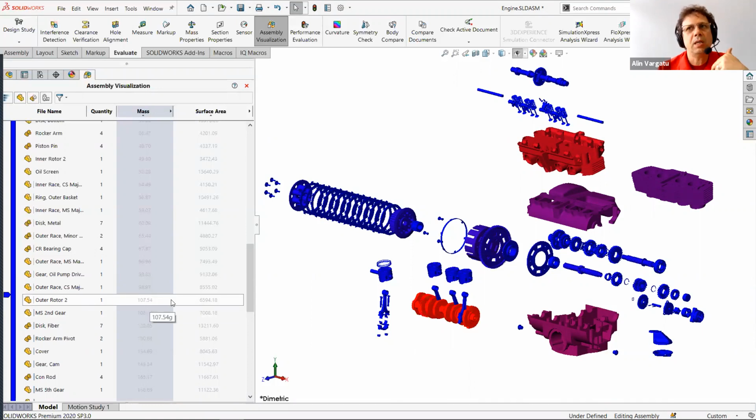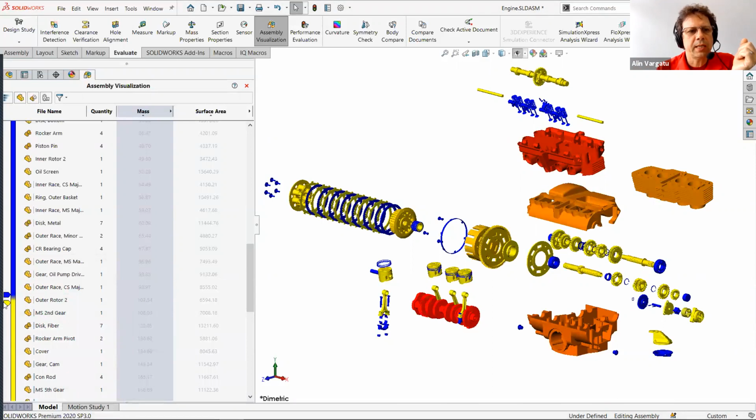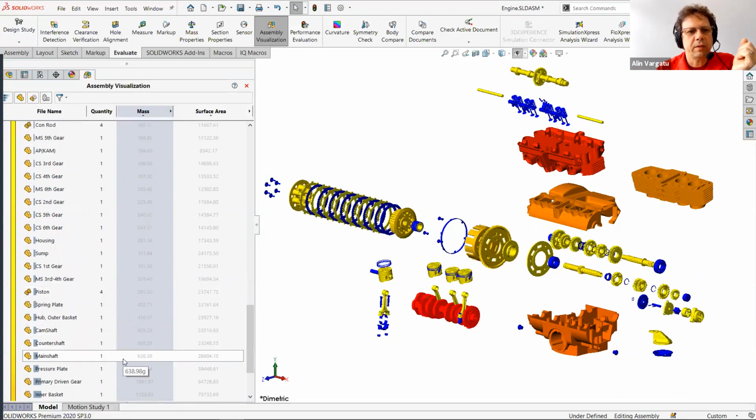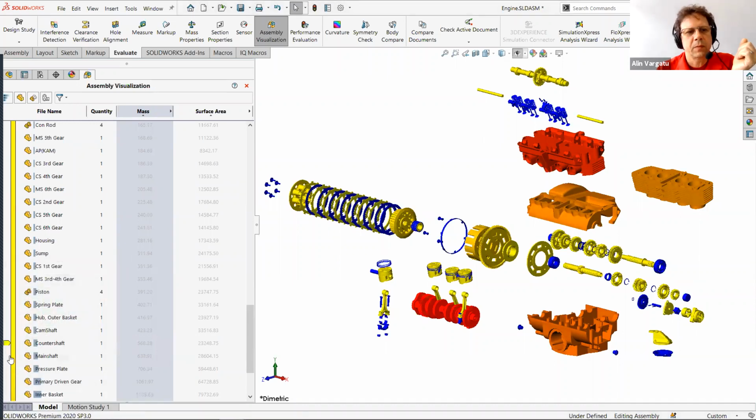Then between 100 and, let's say, 500, maybe you would like to go to yellow. So let's add the yellow slider here. Just click on the left, add yellow. Make sure that it is really in the neighborhood of the blue. And then scroll down and try to find 500. It's somewhere here. I'm going to click again to the left and add another yellow slider, and make sure that this is above 500.